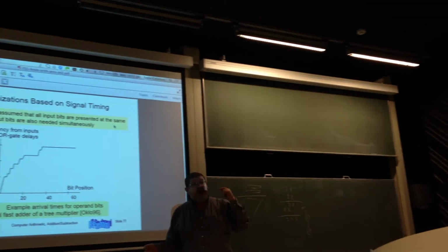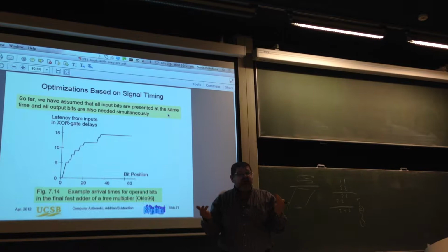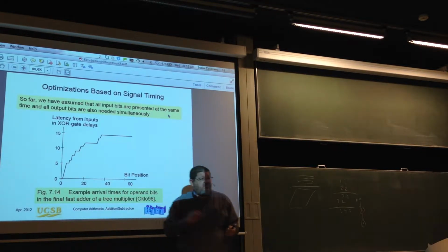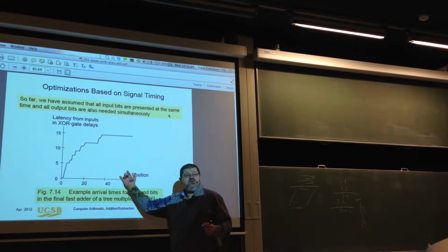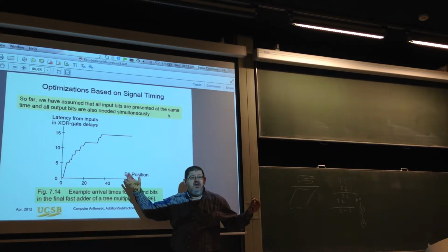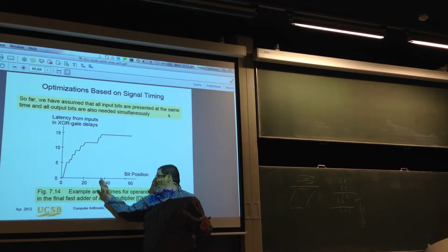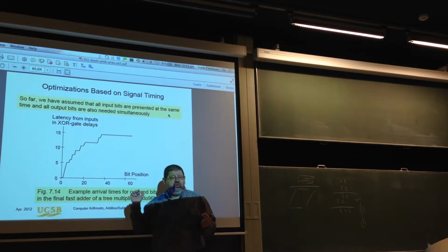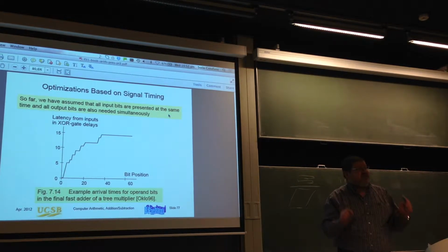Now this adder, as opposed to normal adders in a processor like in an ALU, which get the operands from the register file at the same time, gets the operands in that kind of order: the least significant bits come first and the rest later. This opens some possibilities for optimization, because I should not try very hard to do something with those bits, because I don't know them yet. So I will concentrate on doing the calculations up to, let's say, half of the adder as fast as possible, and be prepared to complete the calculation when the other part comes too. This is a different technique of making adders, an optimization specifically for adders which are part of multipliers.